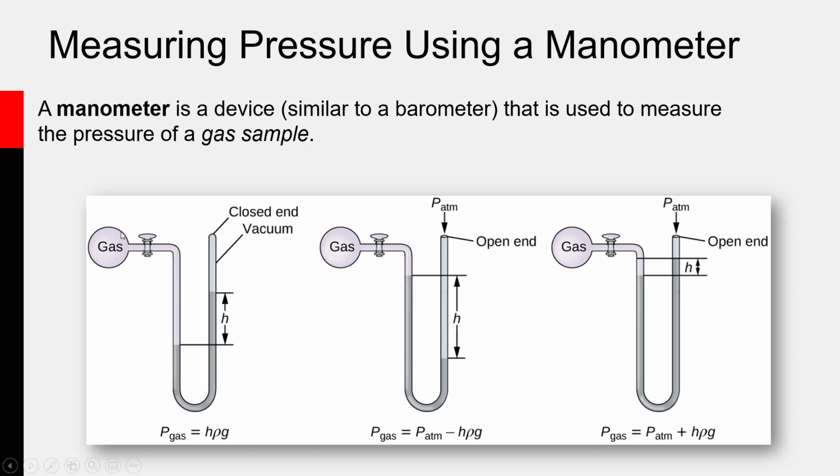It's like a faucet on a sink or any type of pipe. The idea is initially you have your gas sample in the vial over here on the left. You open the stopcock and that allows the gas to flow out into the manometer. When the gas flows into the manometer, it pushes on a mercury reservoir and it raises the height of the mercury on the right-hand side of the manometer by a height h.